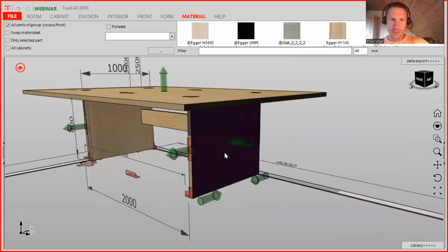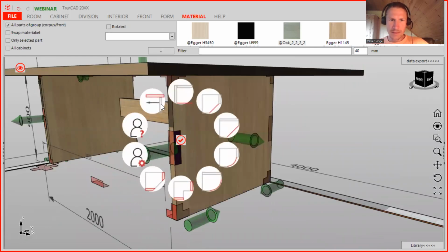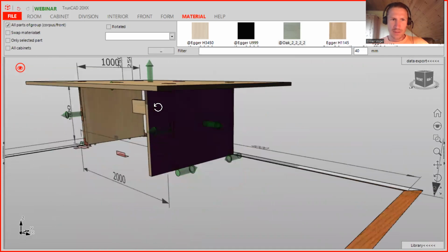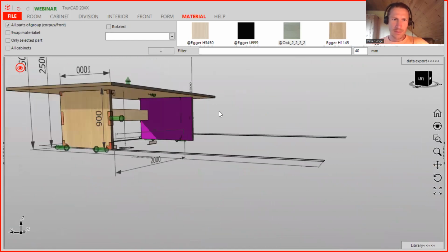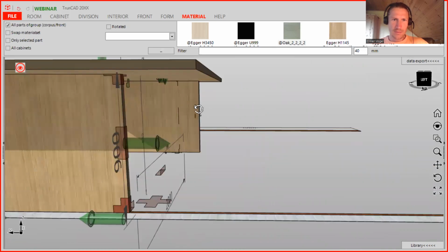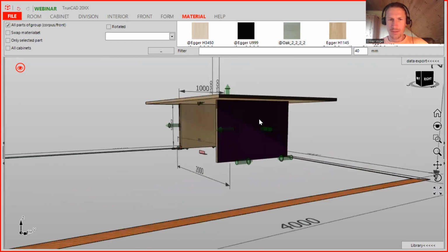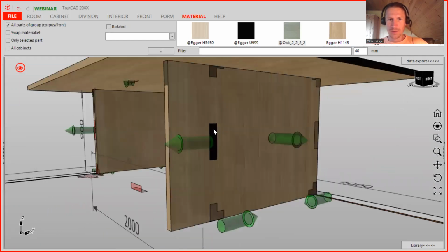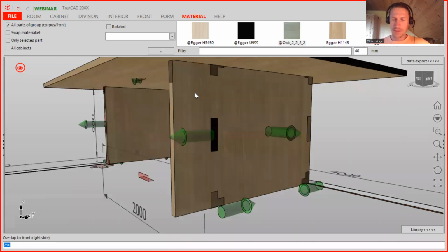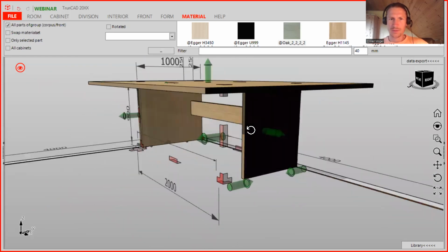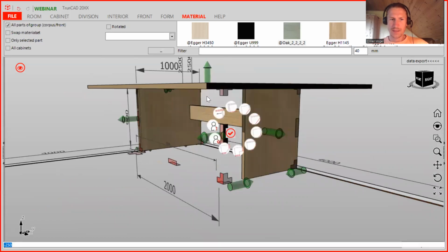Or you can here also go in this smart click, and you can change here the overlap of the side, like 250. And then you see only the right side we have extended, but not the left side. You can do it for top and back. And when you click here again, overlap, and you type in minus 250, then you can also shorten it. So you're pretty flexible in this function.